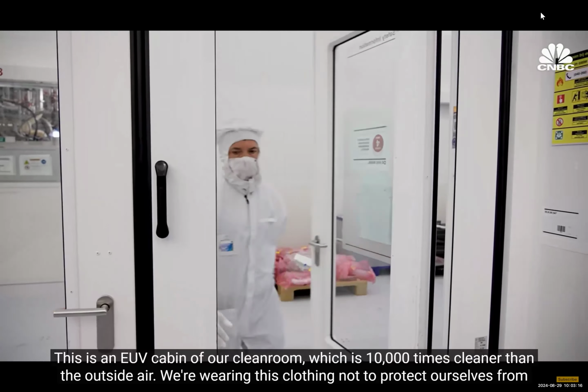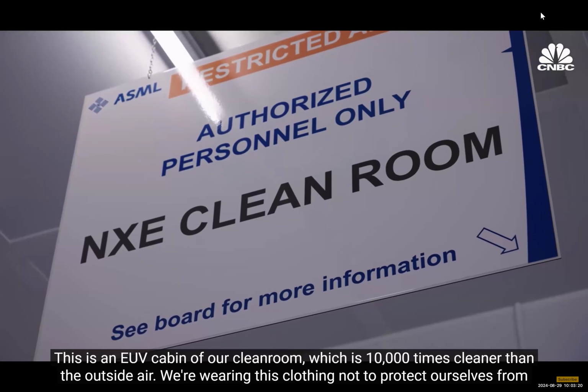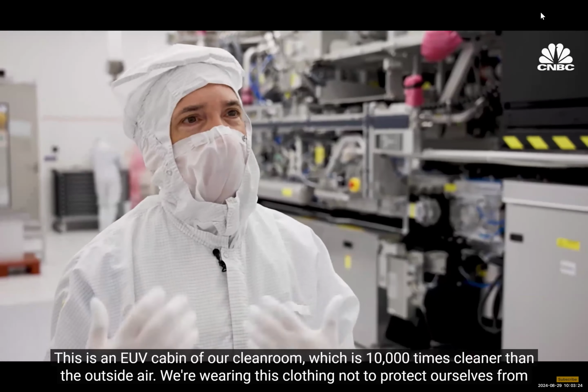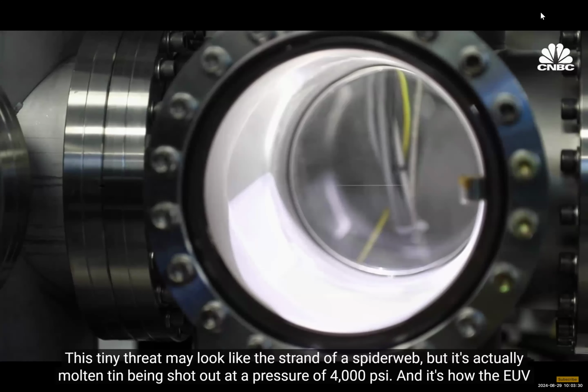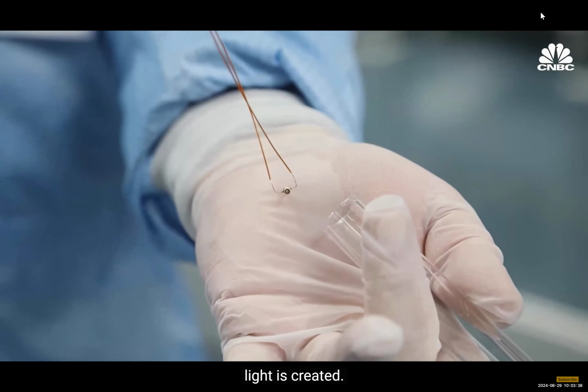This is an EUV cabin of our clean room, which is 10,000 times cleaner than the outside air. We're wearing these clothing not to protect ourselves from the environment, but we're protecting the machine from the contamination that's created by us. This tiny thread may look like the strand of a spider web, but it's actually molten tin being shot out at a pressure of 4,000 psi, and it's how the EUV light is created.